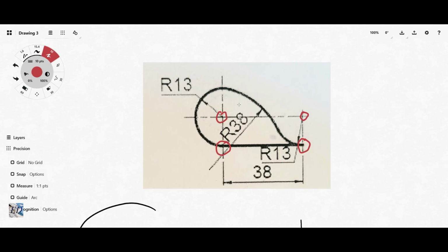So they are touching externally. But if you have a look at this end, draw a full circle here, and then draw a full circle for this one, and then they will be touching internally. I don't know if you saw what I'm trying to explain, but this is the point I'm trying to make: it touches internally at this point, and then it touches externally at that point. So you'd have to go back to the tangency rules and apply them as it's supposed to be done.